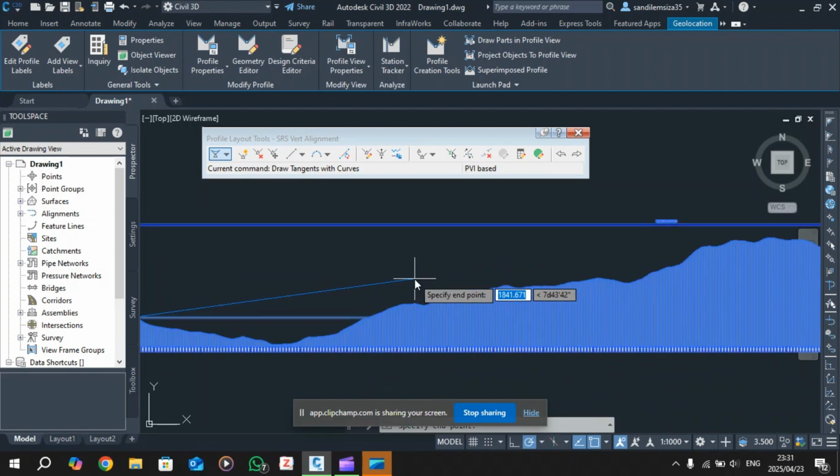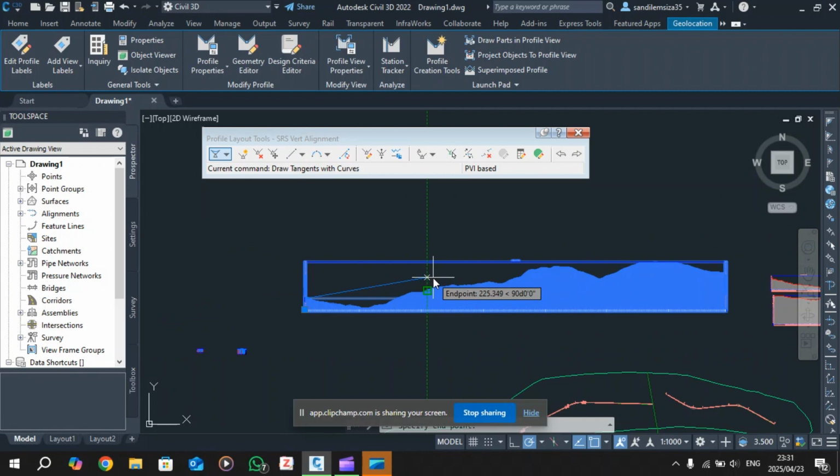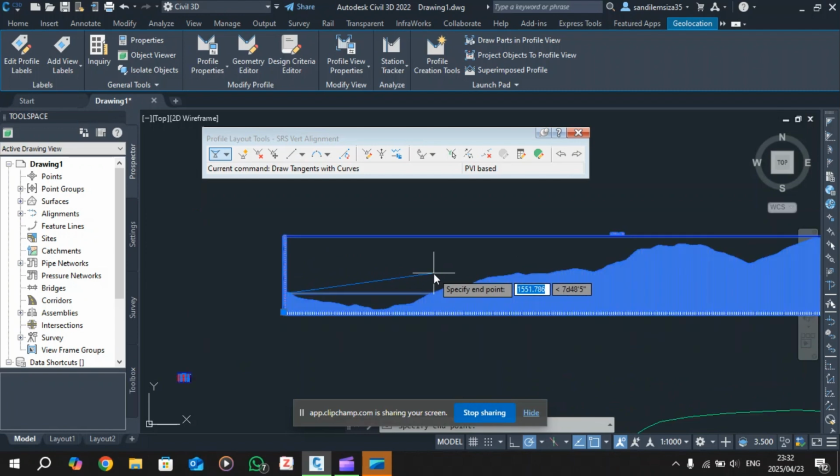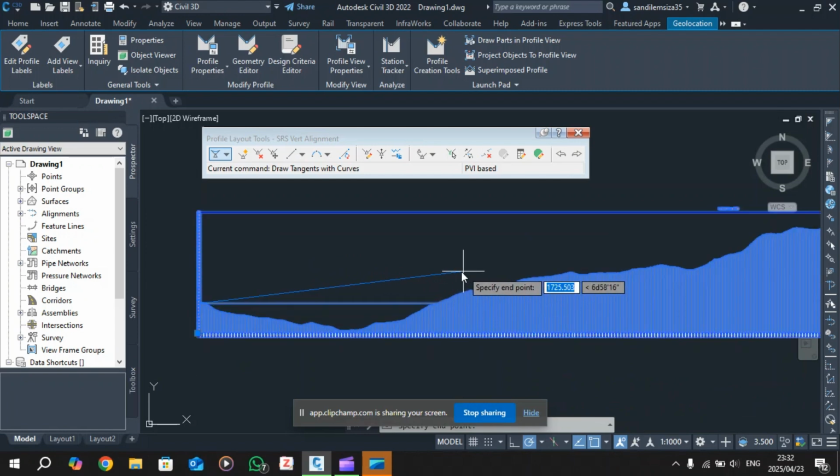You wanna decide where you're gonna be using some of this material. Let's say for example, if I want my road to go through like so, I haven't clicked yet. If I wanted to go straight through, that means the ground that's above my line could be recycled and used in that small space. But you also need to use it sparingly, and you need to properly plan out your vertical curve.